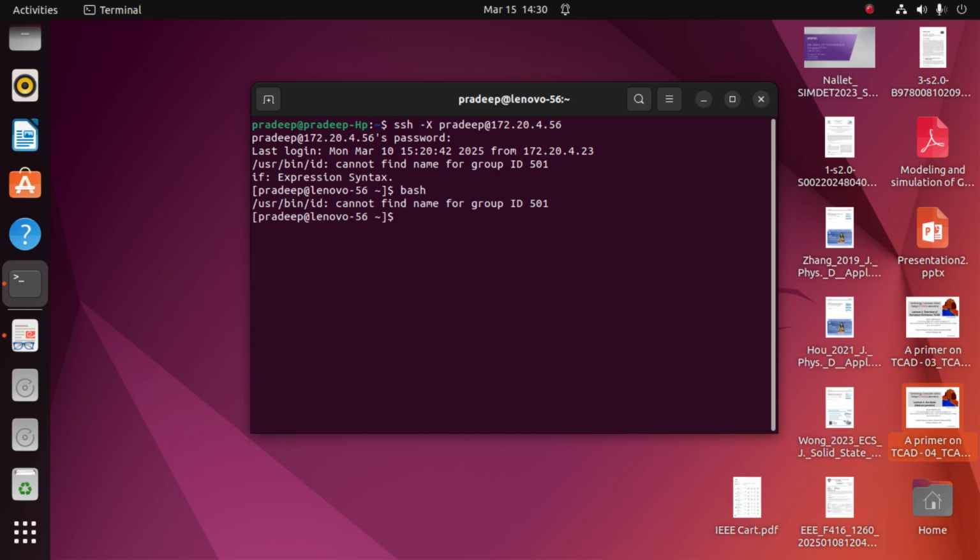So now I have to source my directory. For that purpose I will use my arrow key as I have logged in earlier. In your case, after making the directory, you have to source it like this. You have to type source space /linux_new/scripts/synopsys-2024. Now press enter. Then for invoking the Sentaurus Workbench you have to type swb and percent.